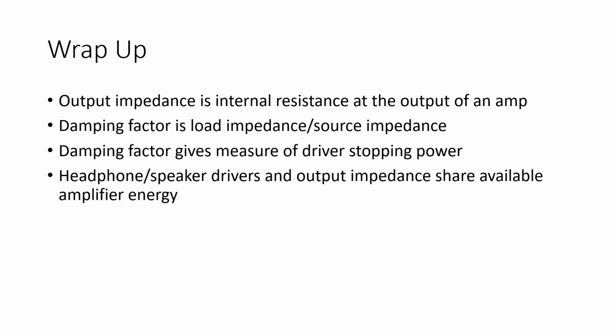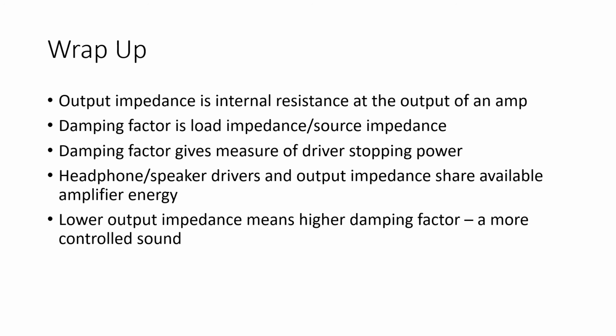All right, and then headphone and speaker drivers and the output impedance share the amount of amplifier energy that's available at any given instant in time. So the more energy that the output impedance takes out and converts to thermal energy, the less energy goes to the headphone or speaker driver to control its motion. And that can have an audible effect. This is why generally lower output impedance means a higher damping factor and a more controlled sound, and is thus desirable.